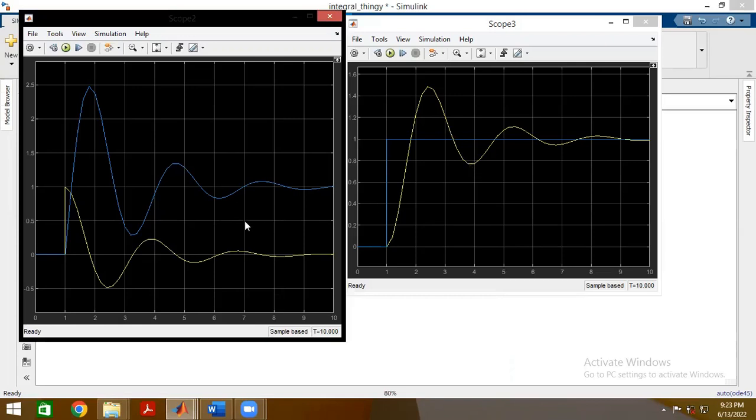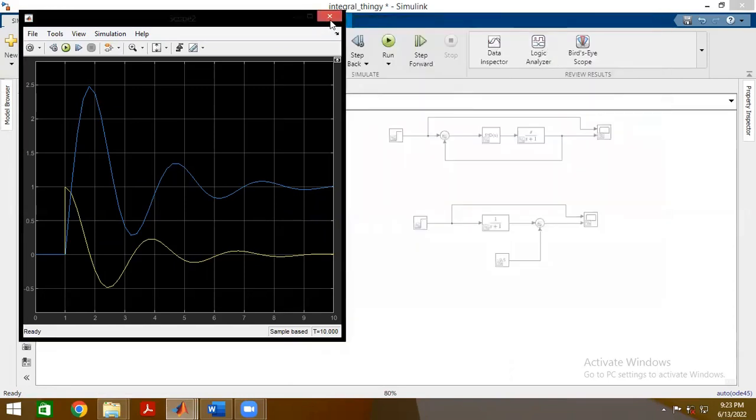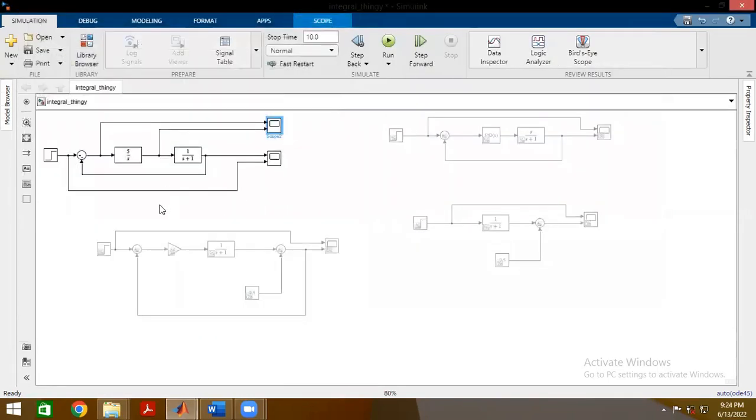And then we see that, oh, we've undershot, and the area now is positive again. It's a finite positive value. So let's try to compensate and go negative. And we overshoot, undershoot until we get to steady state. But we can see right about 10 seconds that we then start following the input signal precisely. So the integral will give you 0 steady state error for a system of this nature. I will talk about system types a bit later on.